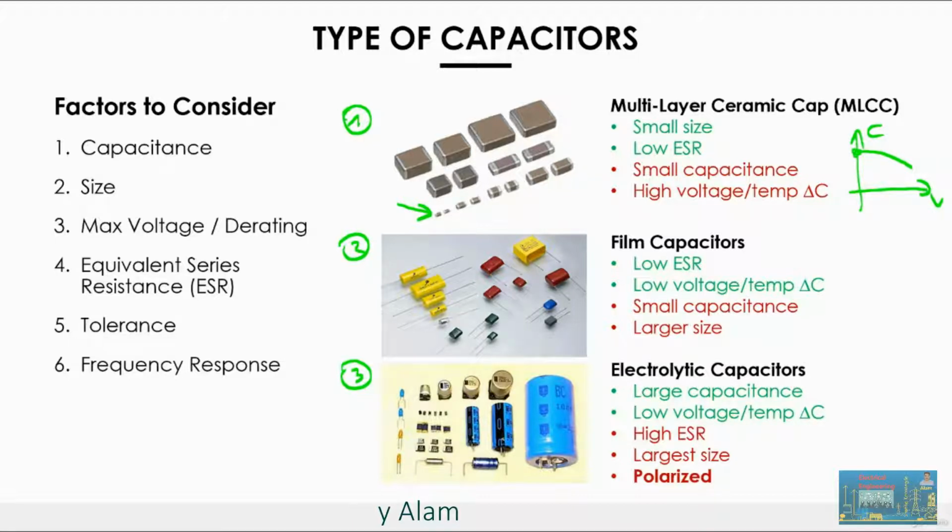And finally, the most important thing that you have to keep in mind, I don't want to call it a disadvantage, you just have to use it correctly, is the fact that these components are polarized, which means that their orientation is not arbitrary. There is a negative terminal and a positive terminal, and you have to make sure that the voltage is always oriented in that direction, otherwise you will break the component. You can see from the picture that usually the negative terminal is the one that is indicated, like this. You see the negative terminal, or this little dot, or this little band. So you always have to make sure to use them with the right orientation. Besides that, it is the component that gives you the highest value for capacitance.